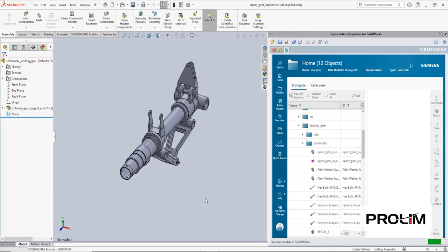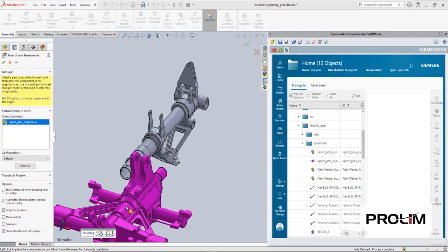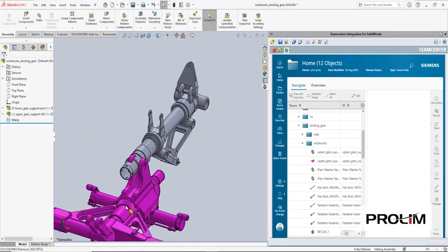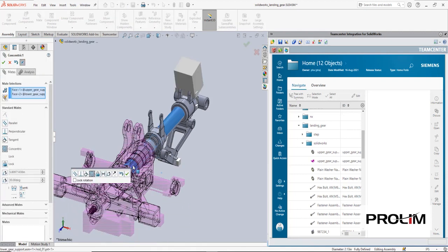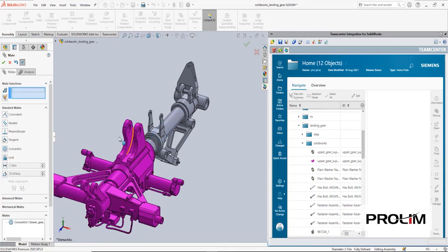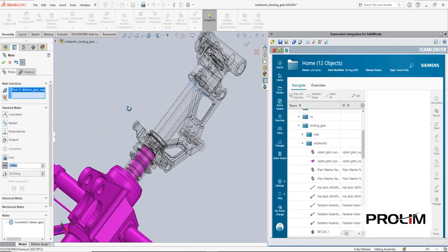In addition to the alignment mate, a dimensional offset is created between a surface on one of the Creo assembly components, and a surface in the native SOLIDWORKS design. Similar constraints can be established against indirectly reused models, but they will not be remembered by SOLIDWORKS the next time the assembly is opened. This is the main advantage of direct reuse over indirect reuse.